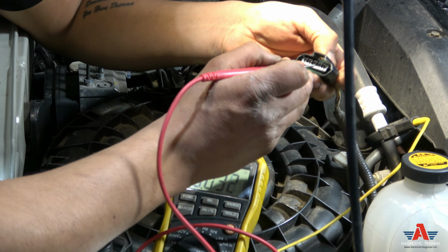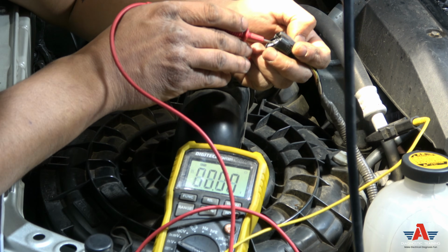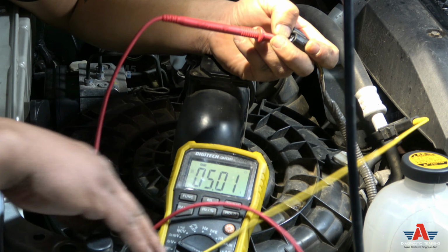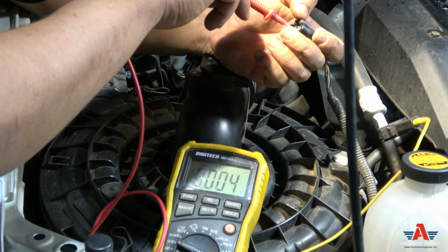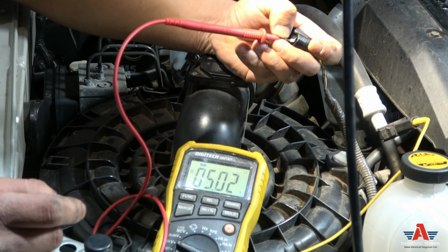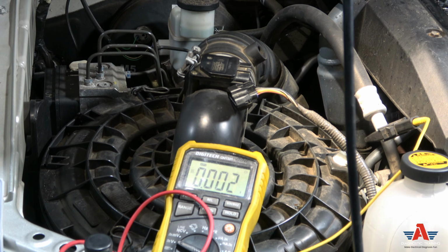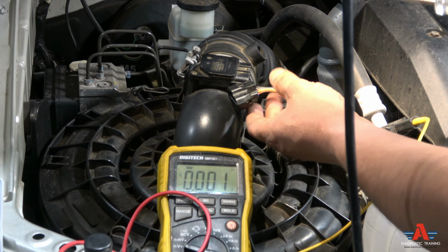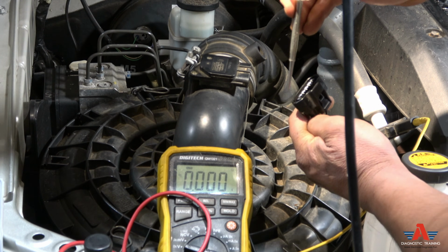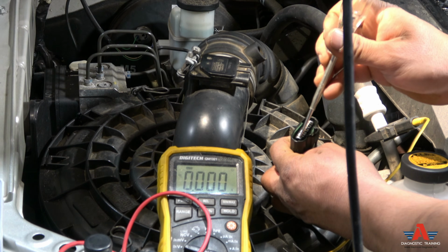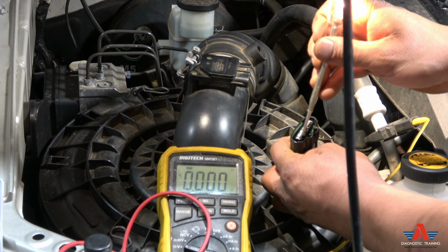Now, yellow and brown, right? I'm going to go to the yellow wire. What do you see? 5 volt. Let me move that lead out of the way for you. 5 volt, right? Right there, 5 volt. What's the other one going to have? The other one's going to have an earth supply, right? So here's my test light. I'm going to touch that brown wire. What do I see? My test light's connected to battery positive. I see earth right there.